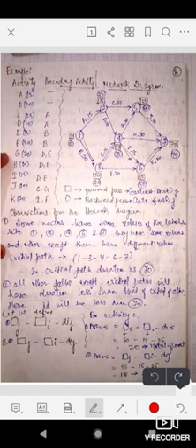So how can we calculate total float? It is very simple. First of all, you have to make a precedence diagram, then make a forward pass, which is written in the square, and then make a backward pass, moving from the end backward. I will tell you once again how to make the forward pass and backward pass.